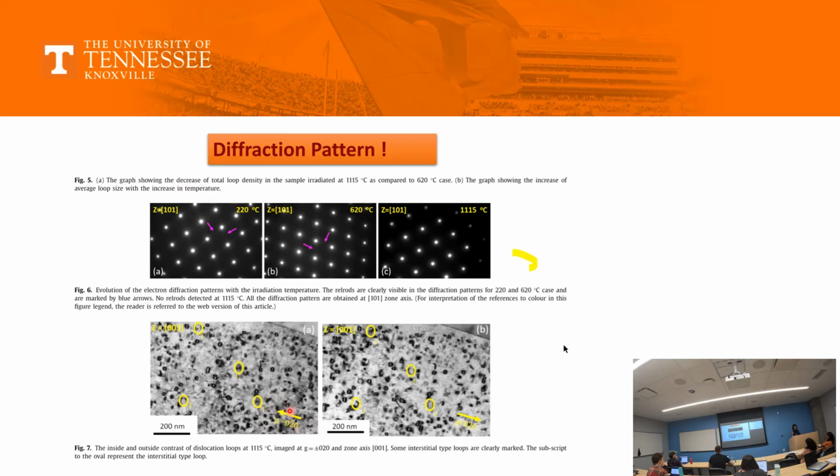And then how do we know B? This is a question. So G dot B, we already know G through these patterns, and B is something that we would calculate by an equation called G dot B equals 0 or G dot B equals 1, where B is nothing but the Burgers vector of dislocation loops, and it could be either perpendicular or parallel. Depending on that, the dot product would change to 0 or 1.